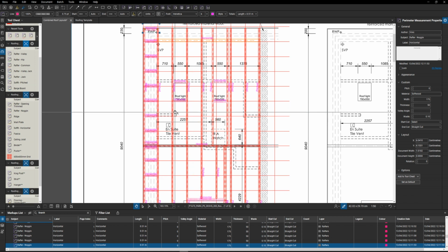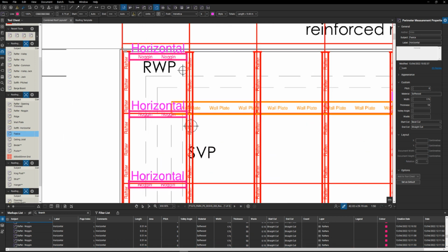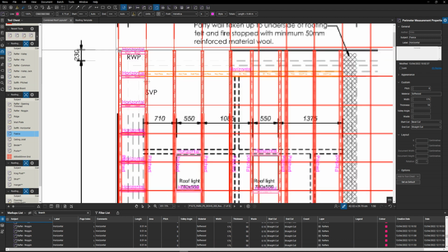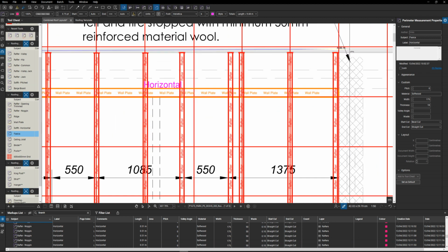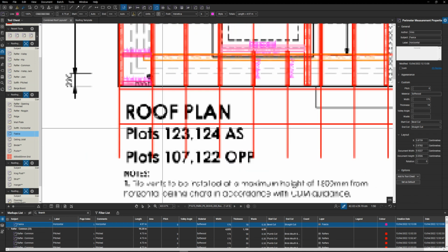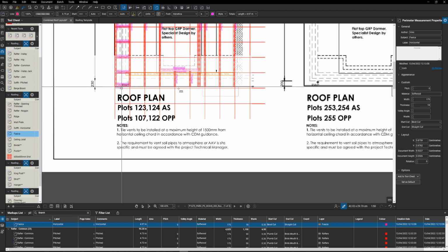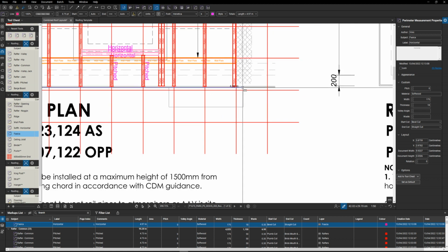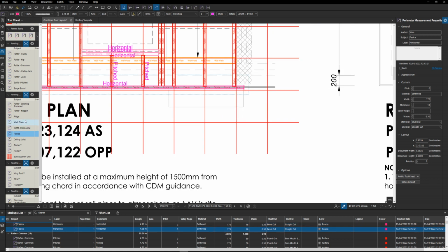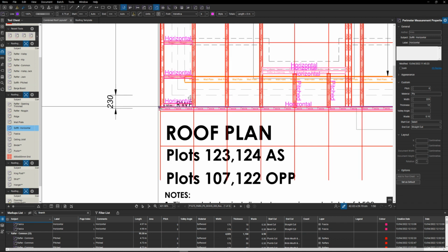Back to the measuring. I think that's all my rafters marked up. Let's do some fascia through here. Let's go to the outside there. Let's take the fascia to the middle of the party wall. We've got some more fascia on this side. We'll put some barge board, some soffits with those, just inside.